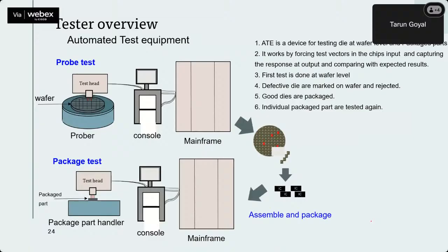Okay. And now coming to, let's see, this is the wafer, and this is how the tester looks, which we call the ATE, automated test equipment. These are the probe head. On the probe head, we will place this wafer here, and these are the test head, and we upload, and there will be GUIs and interfaces like a laptop and desktop. From there it is connected, and it is connected by this mainframe also. So now we are applying power supply, all that the test head requires comes from the mainframe. Vectors are coming from here, the stimuli.